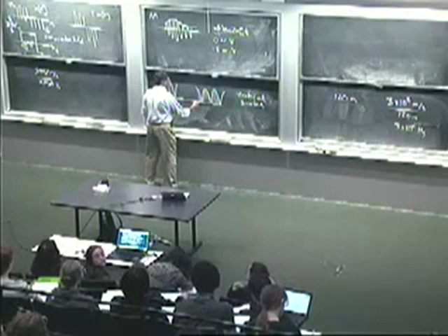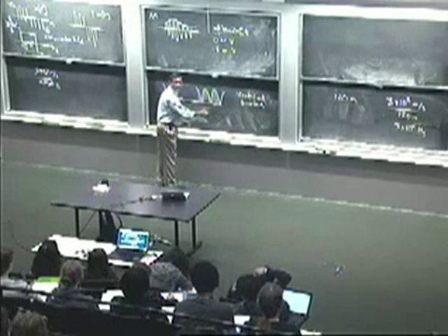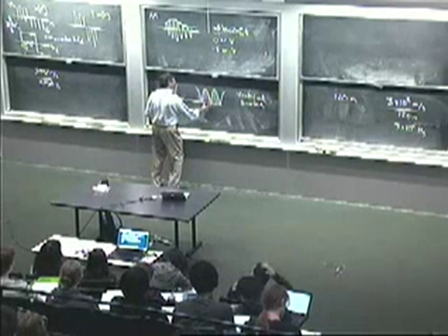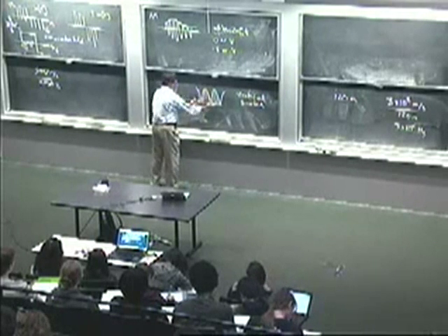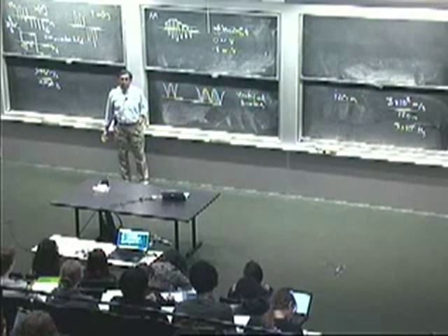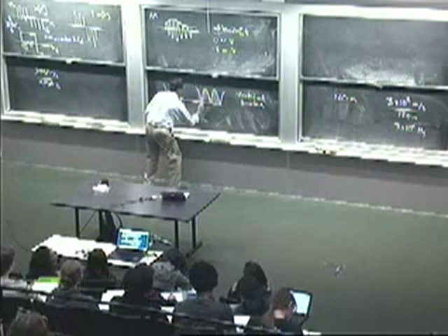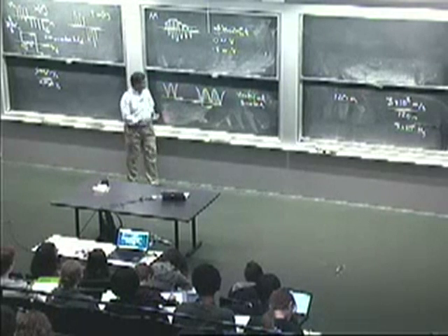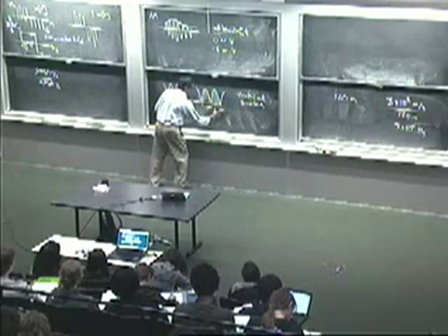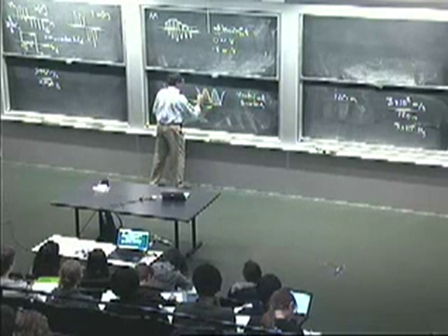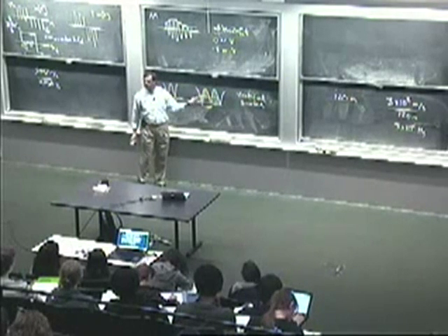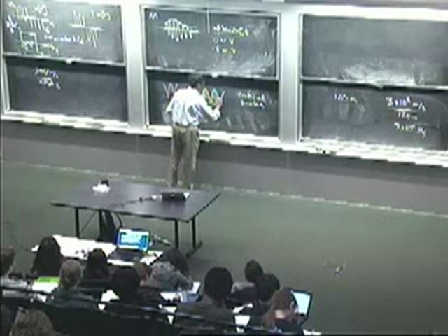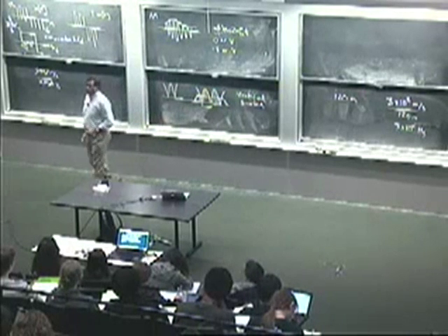OK, so you're saying let's have a sliding window of some kind that looks to see how much of the signal is in there. Is there any window size that will actually give you a constant signal if you're in the body of this? I mean, if you took a window that was equal to a period here, this is periodic, right? While the sinusoid is ringing, it's periodic. So if you took a window of this size and then slid it along, at least in the body of this, you're going to get a constant because you're picking up the average value of the rectified sinusoid. And then near the ends, you're going to get some effects, whatever they are. But that should be enough to give you a good stretch of signal.